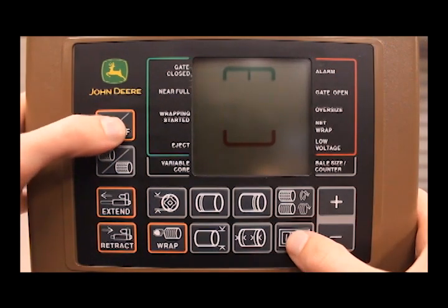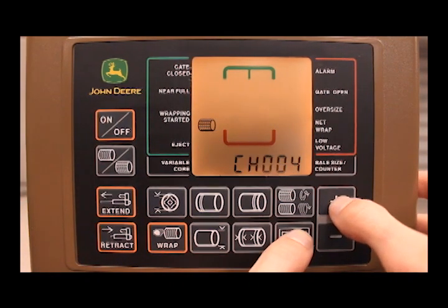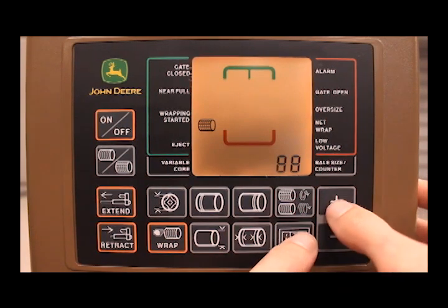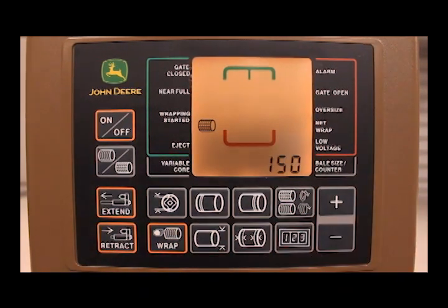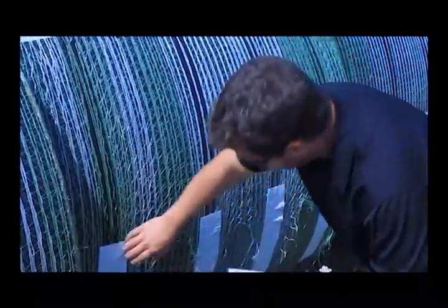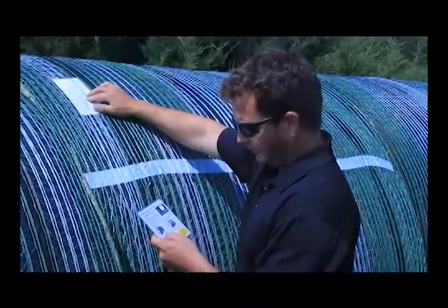Power the monitor back on while holding the bale counter key to enter the 100 level channels. Press the counter key and use the plus key to navigate to the desired channel. Once here, you will need to verify B-wrap settings on channels 34, 35, and 37. Power your monitor off when you are finished to save your settings. These channels control your net tail length or cutoff position, B-wrap seam orientation, and B-wrap metal strip detection.